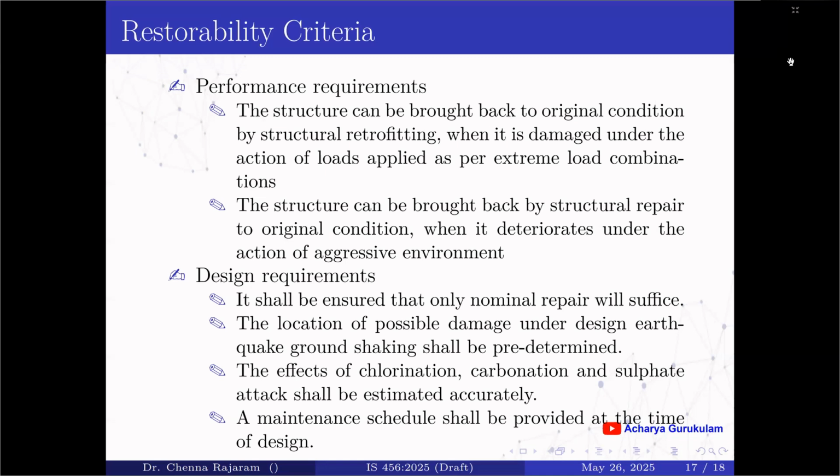The location of possible damage under design earthquake ground shaking shall be predetermined. The effects of chlorination, carbonation, and sulfate attack shall be estimated accurately, and a maintenance schedule shall be provided at the time of design.